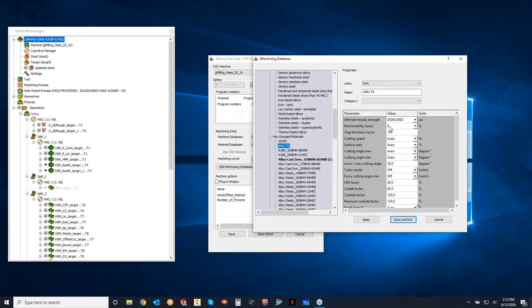In the machinability factor, if you remember from a previous SolidCAM live class, I talked about how you would program it here, and then when you run it you notice that the horsepower of the motor is a little higher or a little lower when you're cutting that material with that same toolpath. You can take those numbers, calculate the machinability factor, come in here and make that change. That's the kind of thing that would be an interplay between the shop floor and the office. With the shop floor editor, the operator on the shop floor can make that change live, save the change, recalculate the toolpath, and now he has iMachining feeds and speeds more appropriate for that material definition.